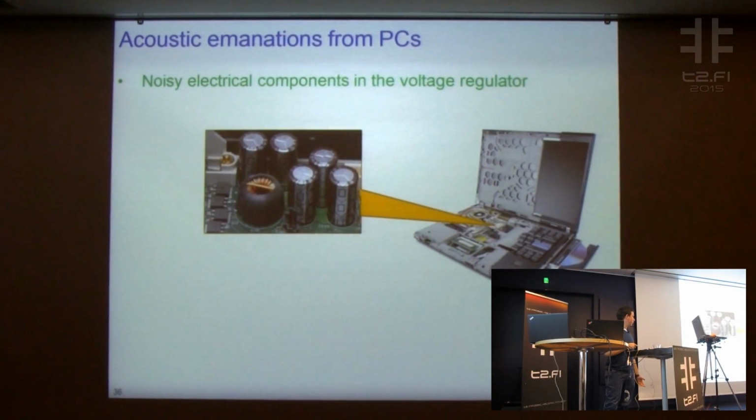If you look a little bit closer on the motherboard, you will see these capacitors and this coil, which are part of the laptop's voltage regulation system. And as these parts struggle to supply the CPU with steady electricity, these parts emit some noises.